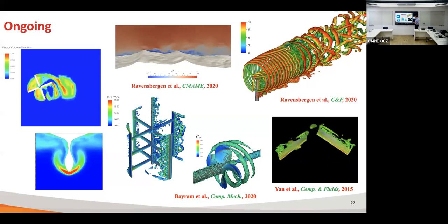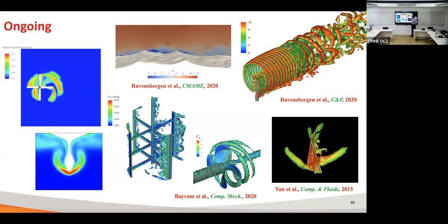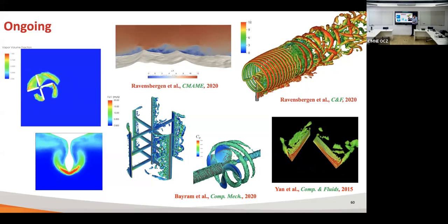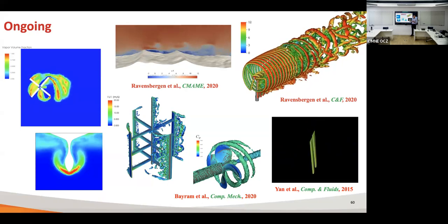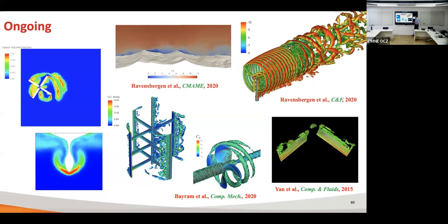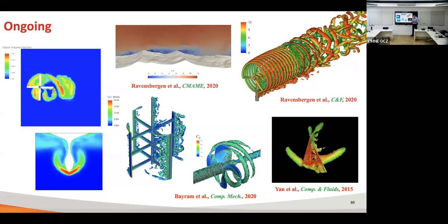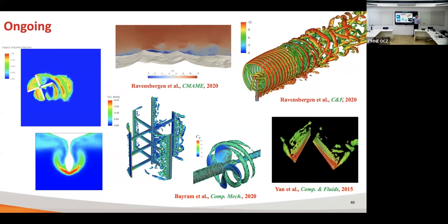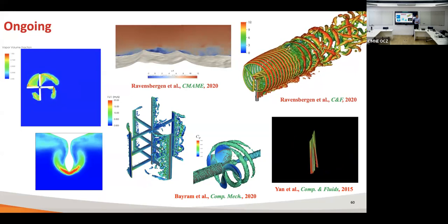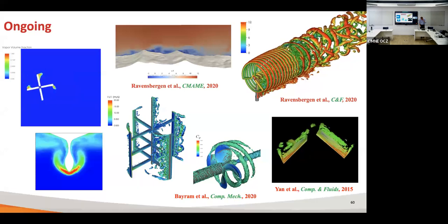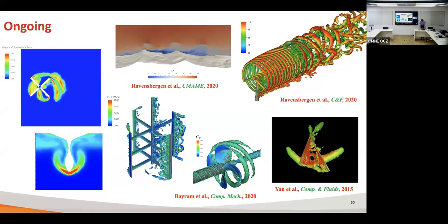in Canada. We also try to develop a multi-fidelity approach for the vertical axis turbine, similar to what we did with ALM for the horizontal. So that we don't have to fully resolve our blades, and we try to incorporate the complex terrain, because when you put this unit in the ocean, there is still a complex terrain that affects your velocity and affects the performance of the system. And of course, we're also looking into the fluid structure interaction.